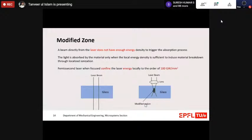It is not absorbed. But when we focus it at a particular point, then for the glass, we see that if the energy at the focal point goes above 100 gigawatts per mm square, then the non-linear effects come into play, the electrons are smashed out of their orbits and plasma generation happens, which results in the modification. Now you can see, as I have shown in the second image, that the focal point could be somewhere in the middle of the glass substrate as well, and there the material gets modified deep inside the glass substrate, and from there we can scan the laser beam and modify the material accordingly out to the surface.